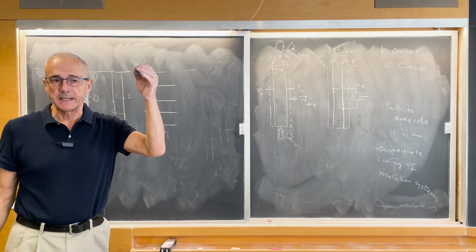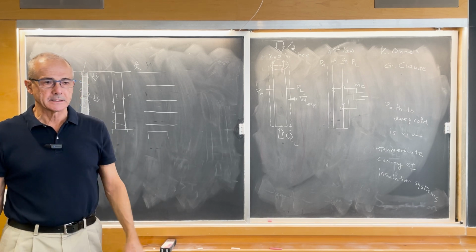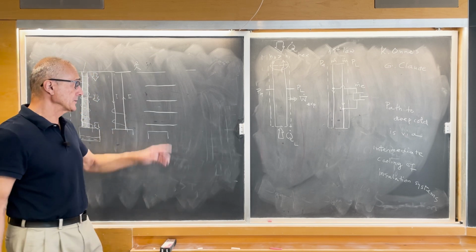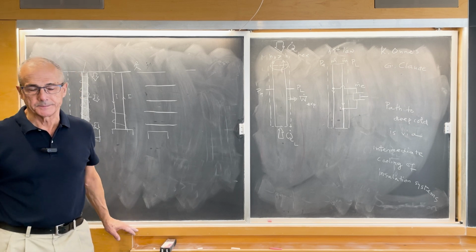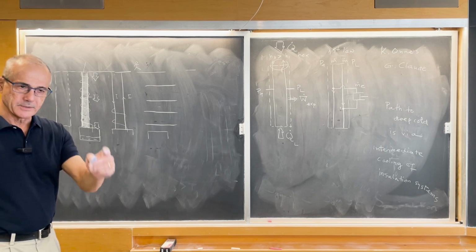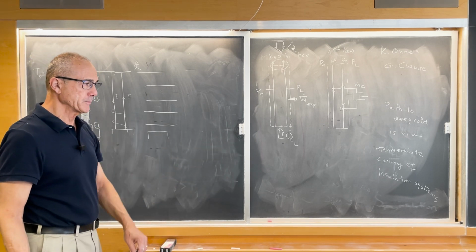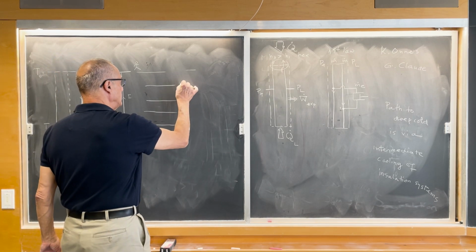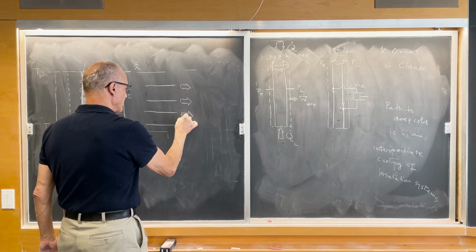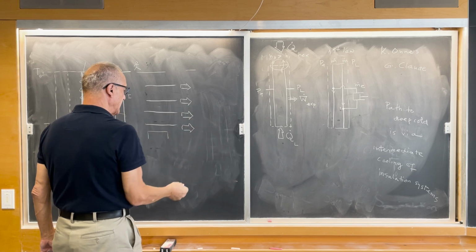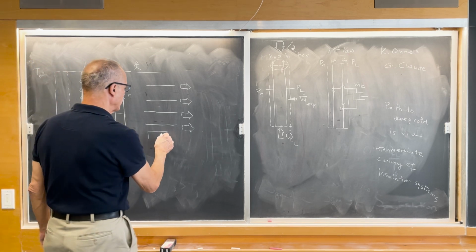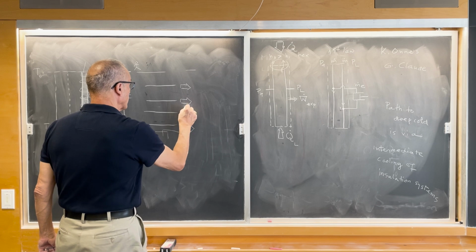For a heat current to pass through even one shield, that heat current is reduced significantly. But if you have a whole series, then the reductions are impressive. But they're even more impressive in terms of decreasing the entropy generation rate, if every radiation shield is cooled by contact with this old acquaintance, which is the cold boil-off gas from the evaporator.